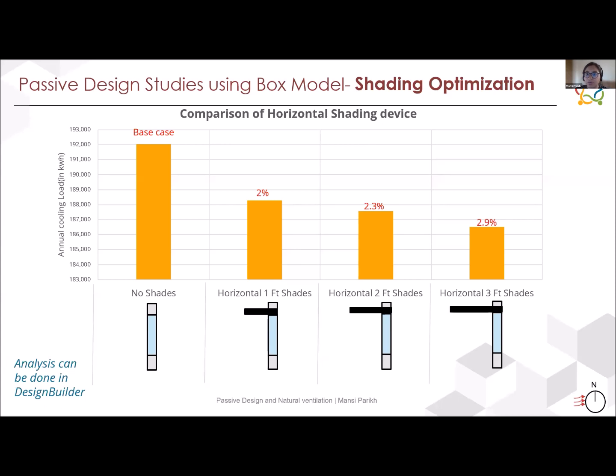So you might have observed, if you sit right next to a window, veiling glares. Probably one of you would have seen that, right? When we are working on a desktop right next to a window, across the day, if there is not proper shading provided, you will feel a veiling glare coming up on your screen, and that probably will be blinding for some part of the day, probably during the evenings or in the mornings, based on the orientation of the window, or where exactly you are sitting.